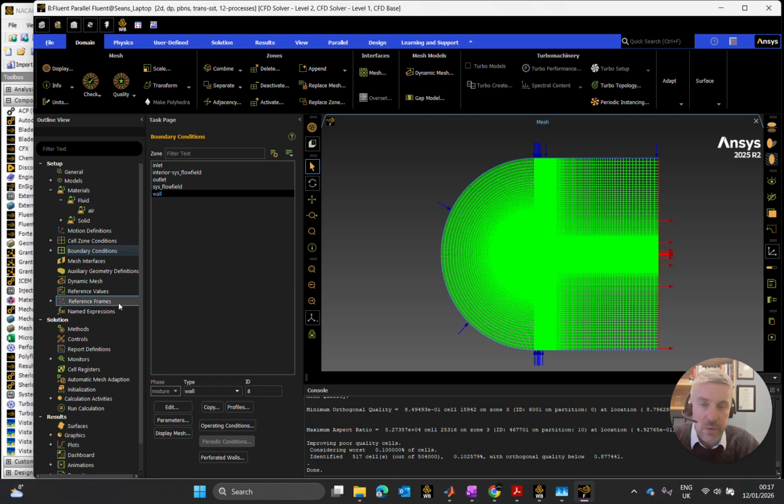I'll either be doing a UDF for the velocity profile, which would obviously be the integral of the acceleration of this airfoil, as the airfoil accelerates from 0 meters per second up to a top speed before drag decelerates it down to a final speed.